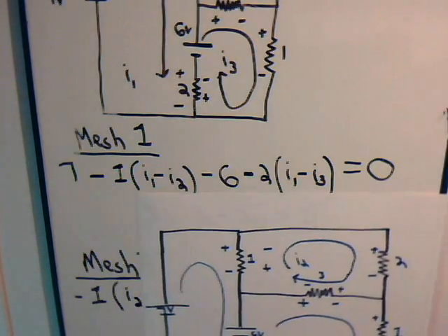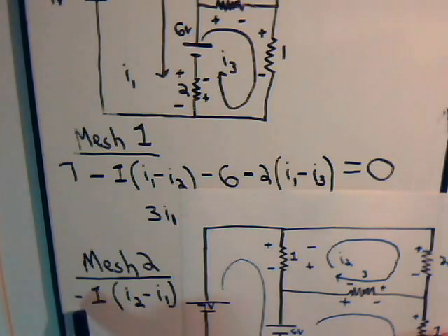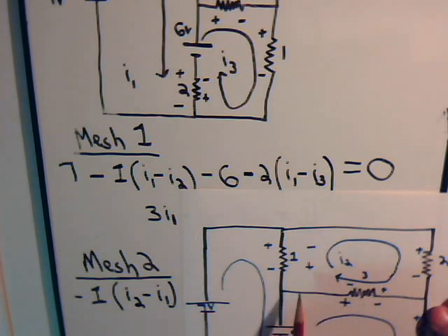Okay, we are considering just this resistor right here going from plus to minus. So that's a voltage drop, so we have a minus sign. And how much of a voltage drop? The value of the resistor, which is just 1 ohm. Only now, we're working with this mesh current. So now we say it is I2 minus I1, written like this.